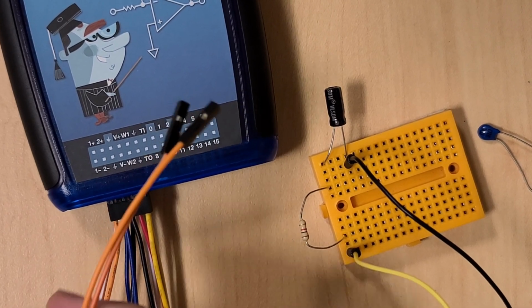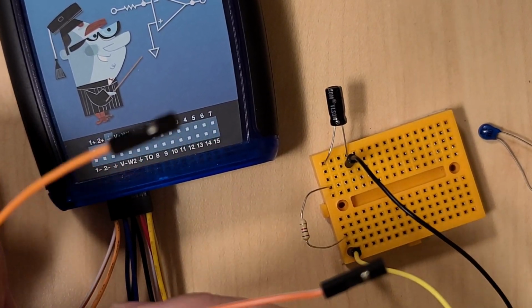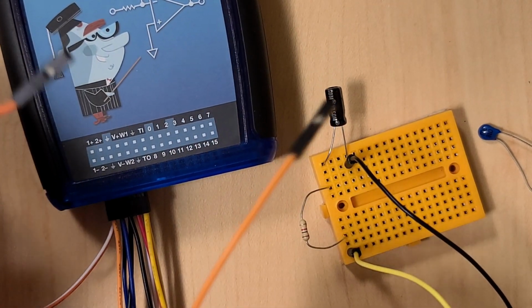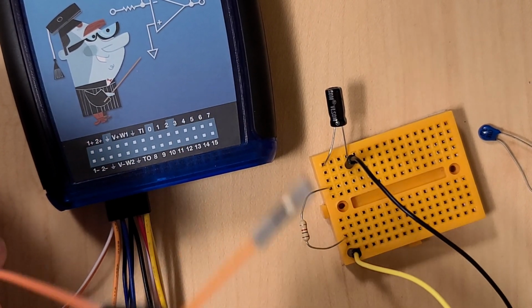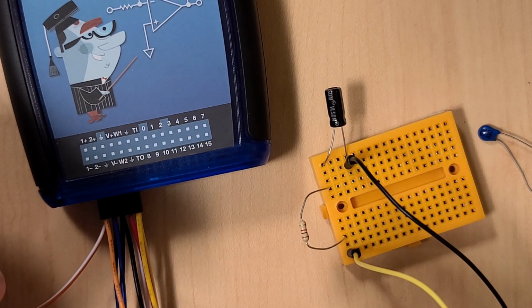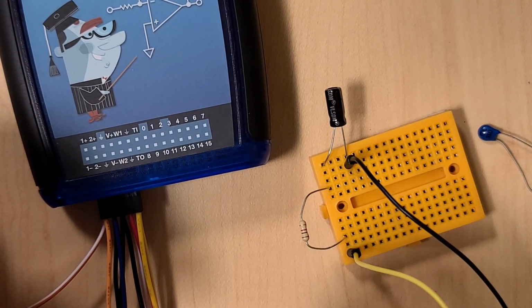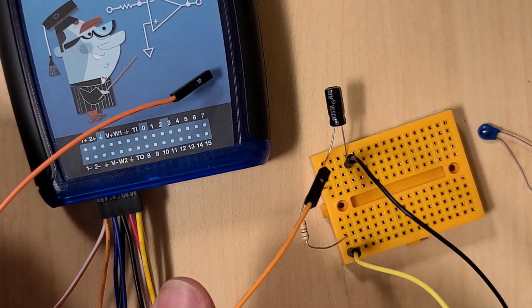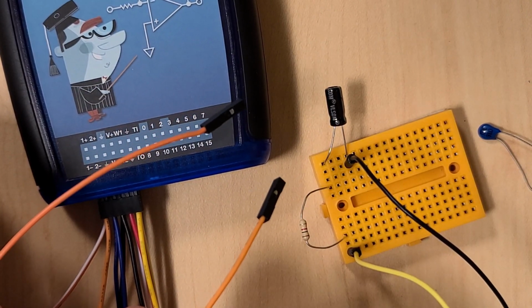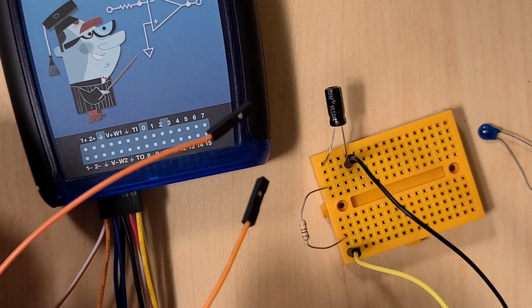So, how are we going to hook up the scope? This scope is differential, just like when we talked about the DMM. The scope is a differential reading. What that means is that it's literally taking the voltage reading between the solid orange wire and this orange and white hybrid wire. The difference in voltage between these two wires is what's going to be measured here.